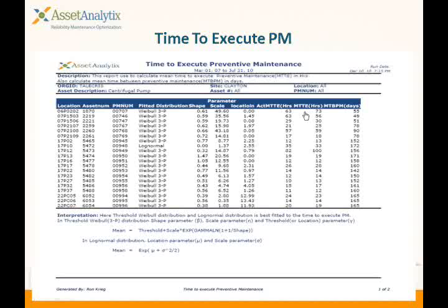These are different calculations. A lot of things will depend on the way the data is gathered. As I said earlier, MTBF can be very difficult if proper data is not captured. But the calculation is very simple. We calculate the operating hours minus downtime, divided by the number of occurrences. So that's the theoretical side of it. And then obviously, how do you calculate operating hours, and how do you calculate the downtime?